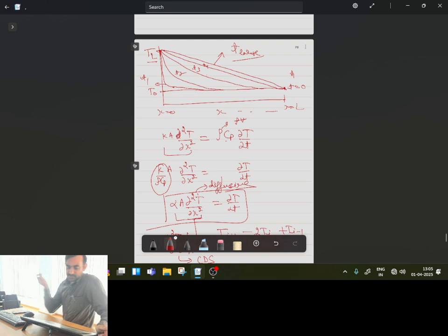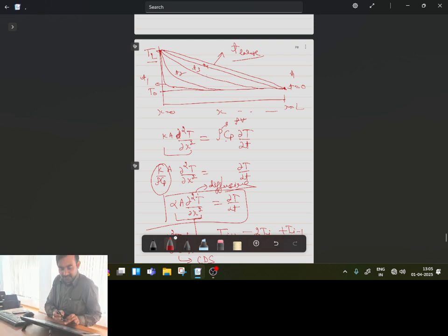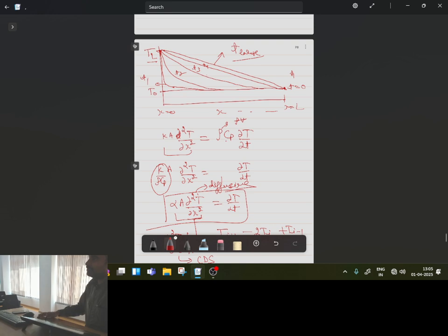So as diffusion propagates uniformly in all directions, whenever we numerically calculate the derivative for the diffusion term, we should also take into account the variation of that numerical scheme in all the directions. We should not take that variation in a certain specific direction, because the physical nature of diffusion is to propagate uniformly in all directions.